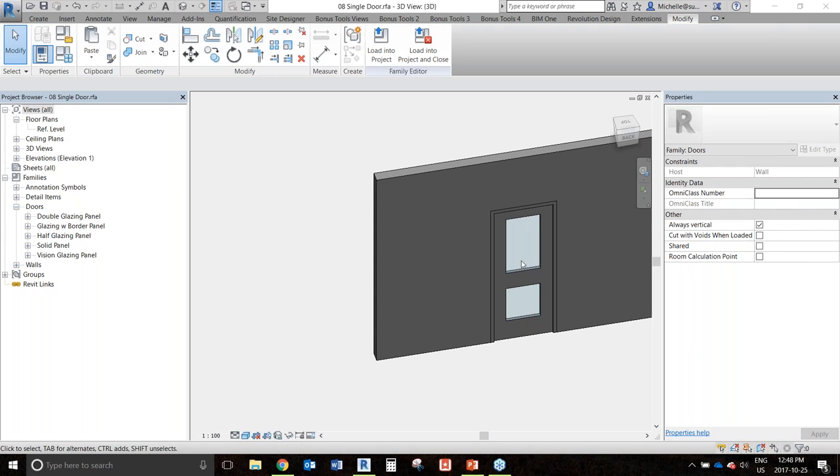Okay, so symbolic lines can also be used for showing clearances of your equipment, or is there a better way to do it? I was thinking that it would keep 3D a lot cleaner. Yes, so this just depends on what you need for clearances. If you don't need to see it in 3D, and the big thing is clash detection here. If you need to do clash detection, you need to have some sort of 3D geometry there so that it can clash into something else.